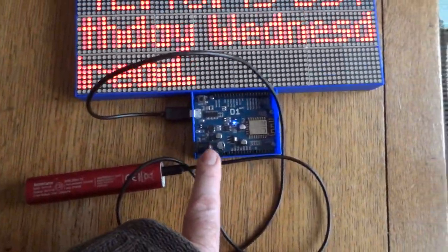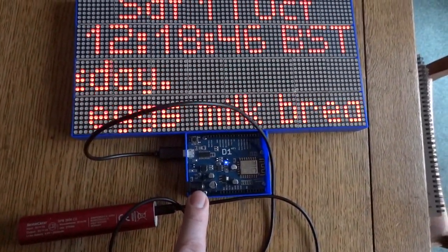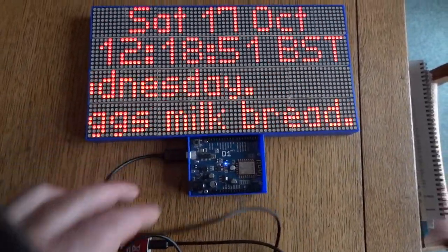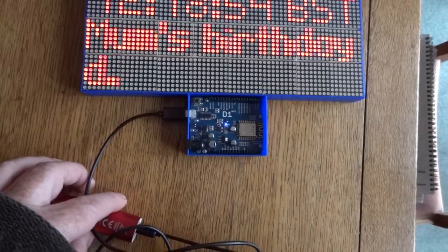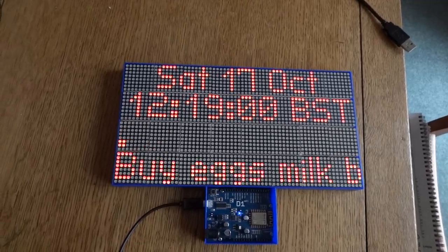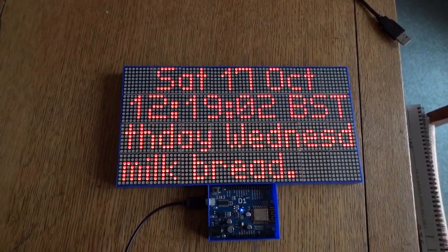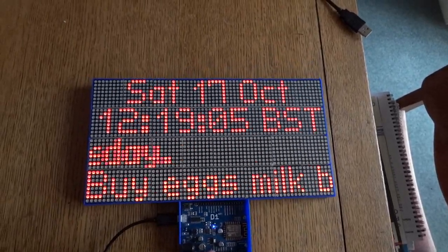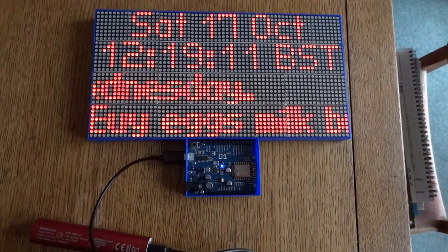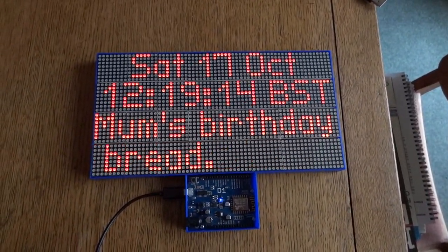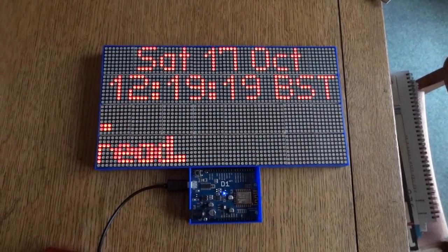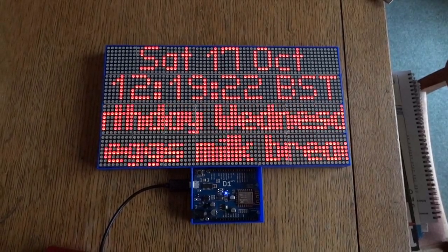Also the Wemos D1, although it's sort of obsolete really, you can get those for $2 or $3, so it's a good thing to buy if you just want to do this. But obviously you could use ESP32 or anything. In fact, the driver I've written will work on any Arduino. It's Arduino IDE I used to do it, and it'll work on a Nano or whatever. But of course you want the internet connectivity to get the time and date and allow the web page update. Although of course you could always put a real-time clock if you wanted to do it on an Arduino.